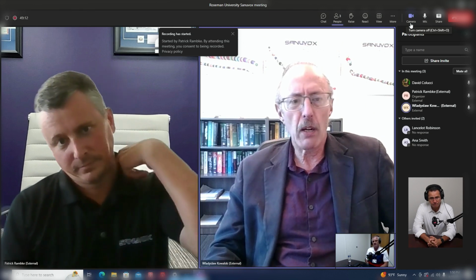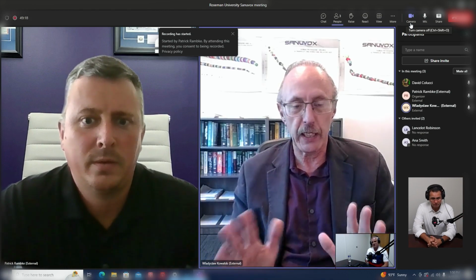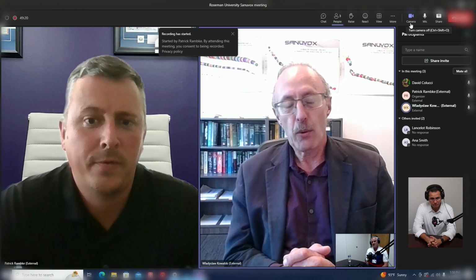Well, we're thinking that we need UV in the duct because almost every building has a fan in the duct. Therefore, we might as well put UV lamps in the duct and get the 1 ACH or 2 ACH of completely clean, disinfected air. The rest has to be made up room to room, that is occupied room to occupied room with UV units, either portable units, upper room units, or far UV units.